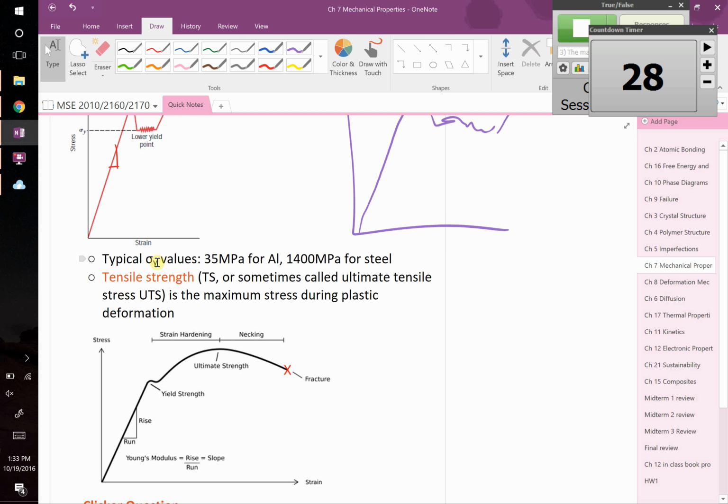Kind of related to that previous question, is it possible for stress to cause a phase change? Oh, absolutely. There's whole fields dedicated to that in material science where they'll put things in what are called diamond anvil presses, a press that applies just ginormous pressures on something, and then they'll try and look at what phase is present using complicated diffraction, and they show that you can change phases by just applying stresses.